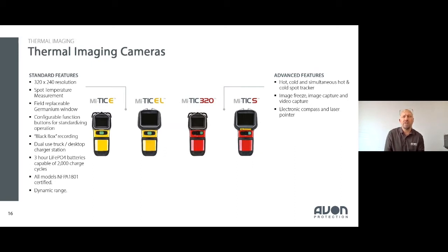What that means in terms of image is that you get a direct relationship between sensor and display. So no lag when you pan across an image. If I was to pan across on some cameras, you get a ghosting effect because the display has to catch up with the DSP that's trying to reduce the size of the sensor image to fit on the display. We don't do that. We have a one-to-one relationship from the sensor to the image.